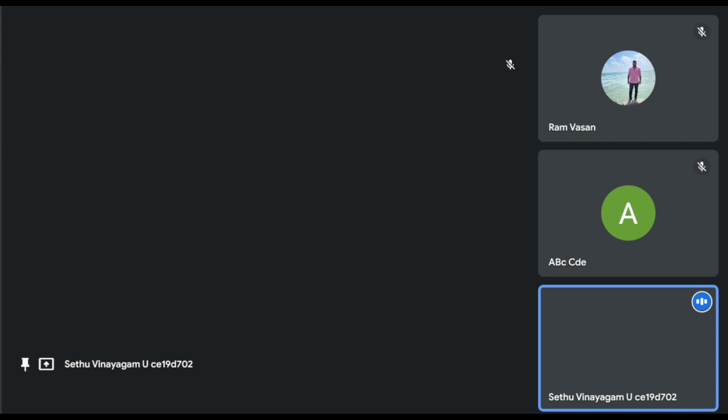So 1 and 2 are based on traffic volume. 3 is based on delays during the peak hours. Okay, and 4 is for pedestrian volume, and 5 is for school crossings. Okay, 6 is the platoon progressions. So we looked at the progression ratio, right? So it is related to that platoon progression.